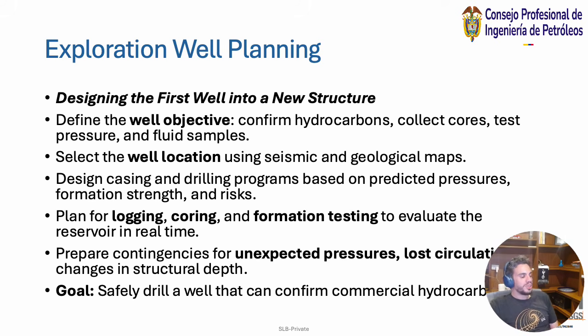And this is the beginning journey of the well, right? We've defined the objective and now we need to define its location. The optimal location, usually you're picking more than one well, so in the exploration phase, you'll do 1 or 2 wells or a few wells, depending on the size of the project. And you also want to know how you're going to build this well, so how I'm going to design my casing, what drilling programs am I going to follow, based on the pressures and the formation strength and the risk?